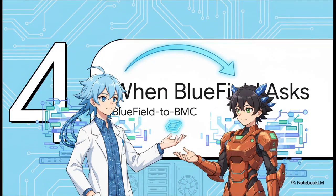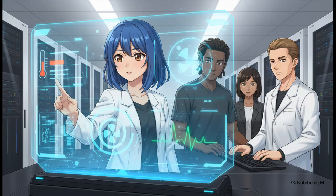All right, time to flip the script. Let's look at the other side of that conversation. What happens when the Bluefield ARM is the one that needs to ask the BMC for something? So why would you do this? It's simple. This is your direct line for checking on the system's health in real time. If you need to know a temperature or check a fan speed or get any other sensor reading, you'll do it right from the Bluefield console by sending a query straight to the BMC.